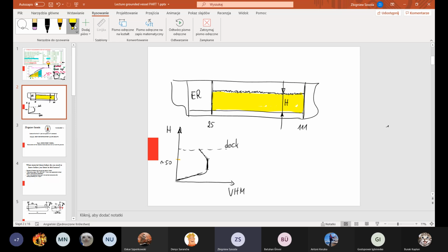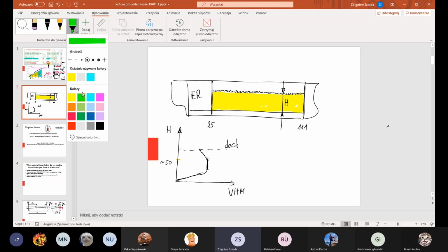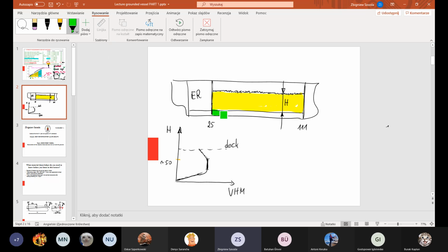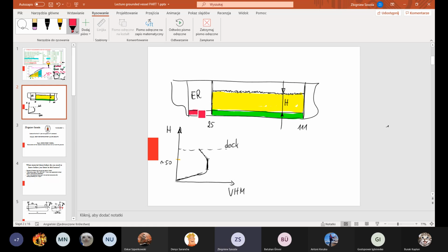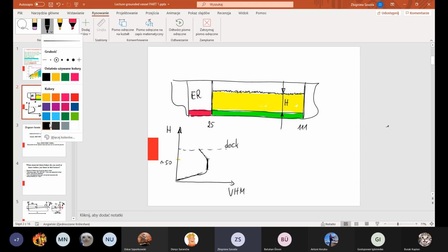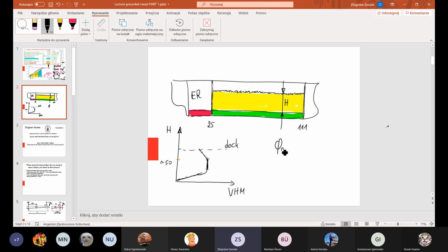Okay, in our case, all ballast tanks, double bottom ballast tanks, were filled in, and probably somewhere here we have fuel oil also in a double bottom tank. It is my imagination of the situation. And the result of our calculation was that the angle of heel, which is caused by shifting of the grain, was bigger than 12 degrees. And it means that this criterion is not satisfied.